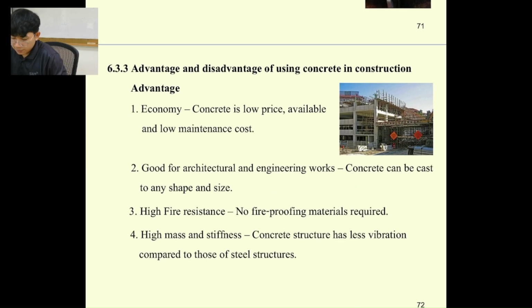The advantage of using concrete is first the economy. Concrete is lower in price because the materials can be found easily. For example, you can get crushed stone from anywhere, you can get the sand from the rivers, and the cement can be bought easily in the market.